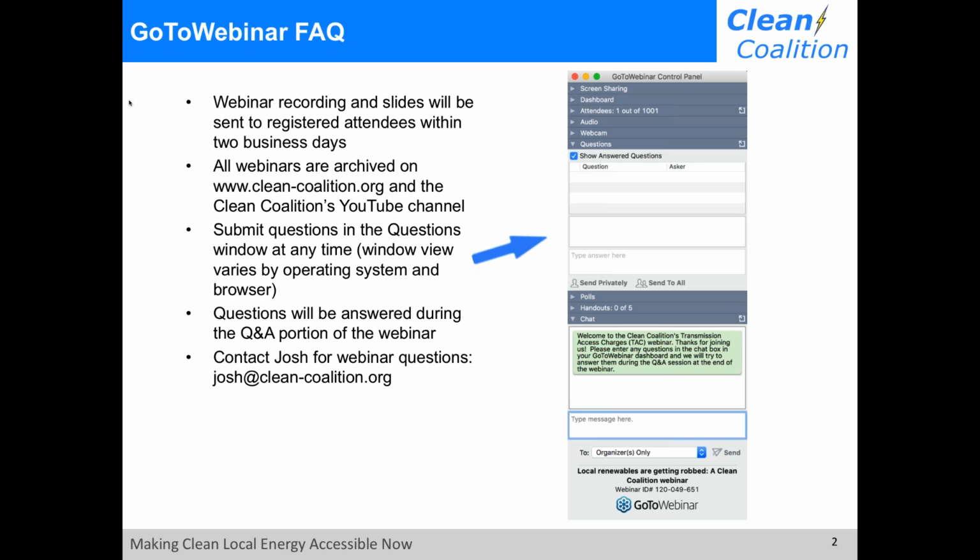The reason the ICA is being developed with the specificity down not just to each line section, but to each node within each line section, is to provide that information in great detail. But the hosting capacity value there will tell you what the aggregate capacity is, regardless of whether that is met or used up by a single application or 100.